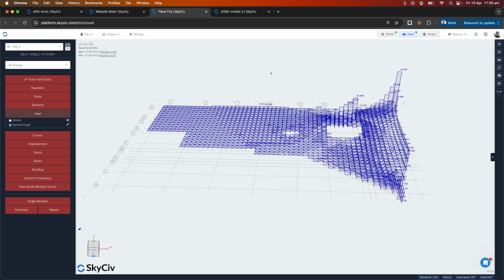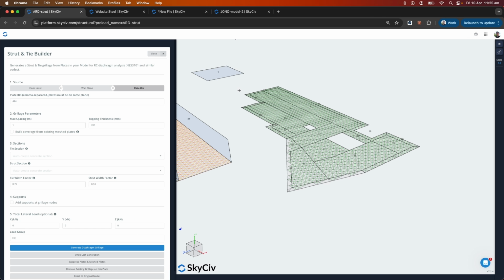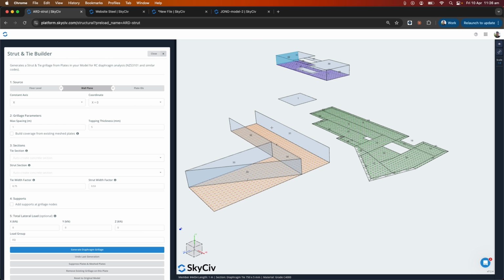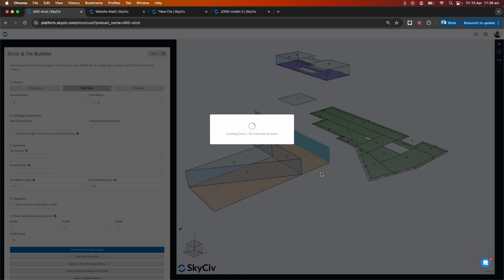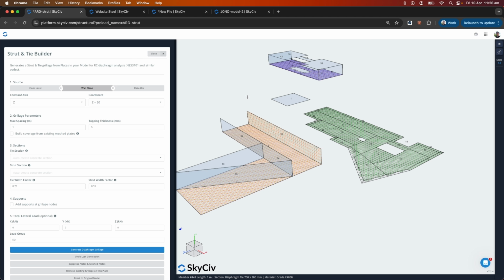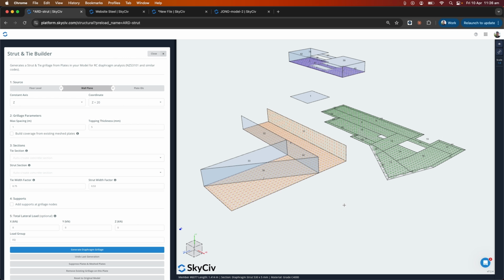And that pretty much covers most of the tutorial. In this example, you can see a fair few different cases. I can also show the walls, how you can control the walls, or how I just use the plate IDs as well. But you can see I've got all my X in X equals 0, and it's automatically detecting where I do have plates. So it's picked up that is a plate there and that one there. I can also do in the Z direction. So if I want to do, say, plate 31, I can find that location and generate the grillage from that as well. So it does work in both planes. Obviously, the most common use case is a slab. But yeah, it does work in plates if you have shear walls or things like that.